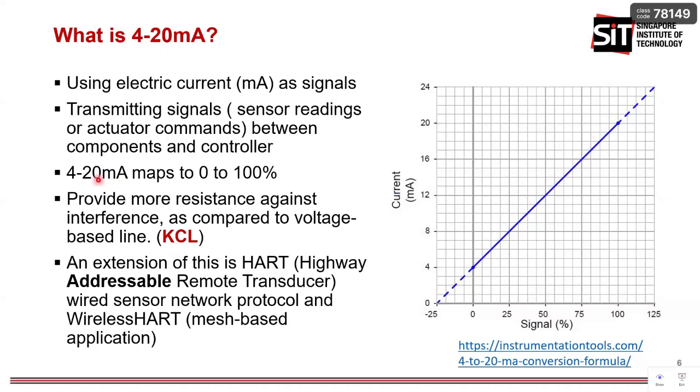Okay. And there is a further extension of the use of the 4 to 20 milliamp standard. And this extension is called HART, H-A-R-T. HART refers to Highway Addressable Remote Transducer. I highlighted addressable because when you see address or addressable in this case, it refers to the device having a unique ID. And with a unique ID, you can actually address the device or call upon this device to interact with you. In the case of doing data exchange, for the sensor, you could be requesting sensor data and so on.